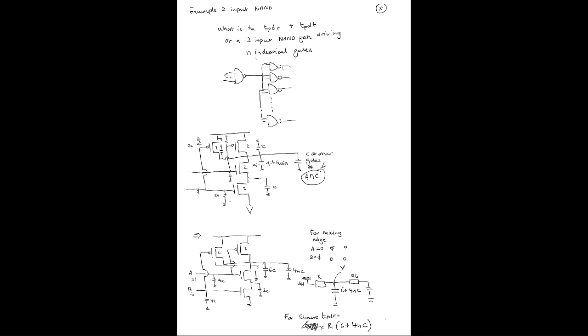I won't go through the examples again. Here, what I did is went through a 3-input NAND gate, and we calculated all the capacitances and the resistances. And then I did another example where I had an input, a NAND, feeding some other NAND gates, and actually worked out what all the capacitances were, and showed what at least the Elmore propagation delay, or the Elmore equivalent circuit, is in order to work out the effective propagation delay for a rising edge signal.